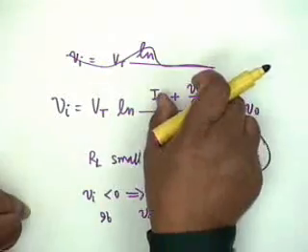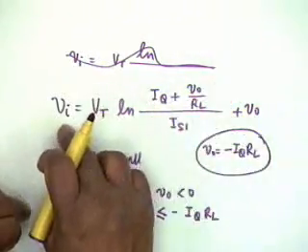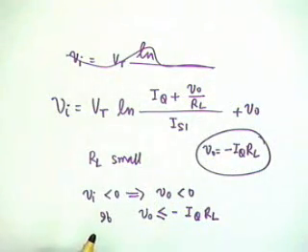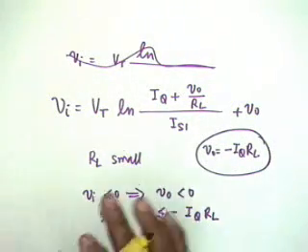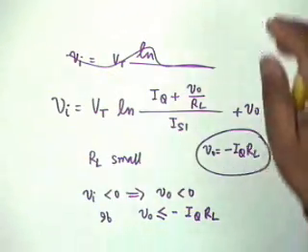Under this condition, this will be 0, log of 0 would be minus infinity, and therefore Vi would be minus infinity, and infinite negative voltage is required. Obviously, this does not make sense. There must occur something physically. If we look at this circuit, what will happen? Pardon me? Say it loud, even if you are saying it wrongly. How does it matter? Q1 will cut off. Why? That's a good answer. Why?